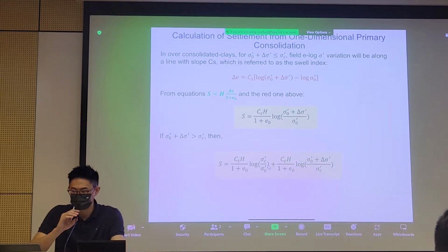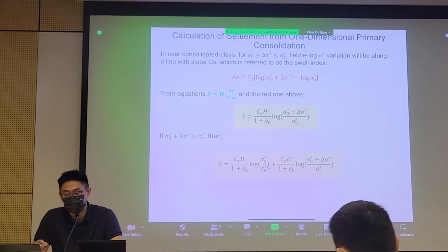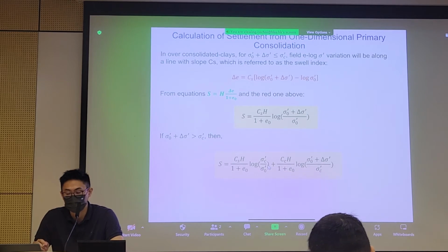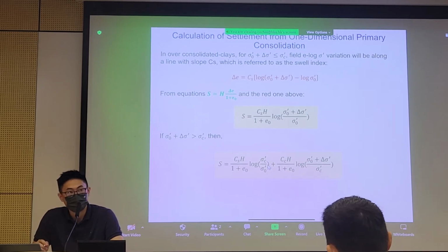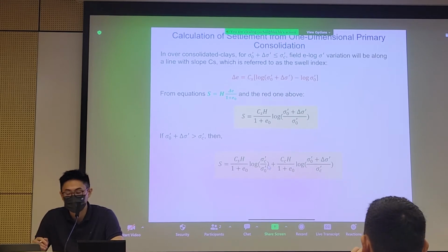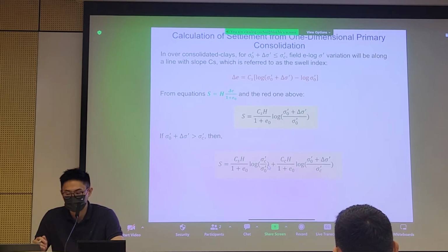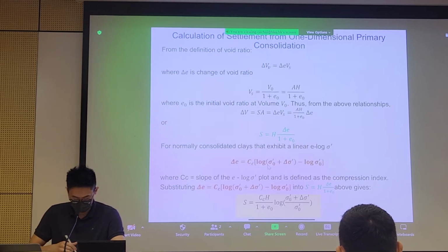So in the last class, we derived three equations. Particularly, these are not complicated, right? They just describe the linear relationship of your compression curve, your swelling curve, and if you like to combine both of these during unloading, reloading, and back onto the virgin compression line, then you can use the equation at the bottom of the slide. So in essence, if you recall, there are three equations.